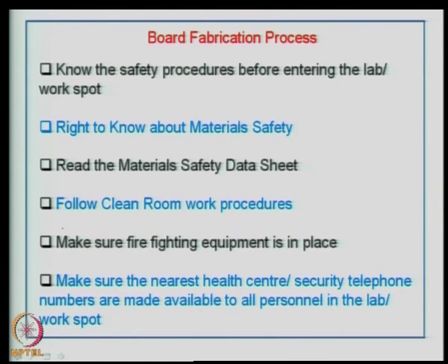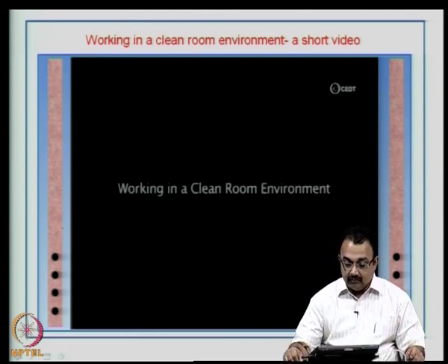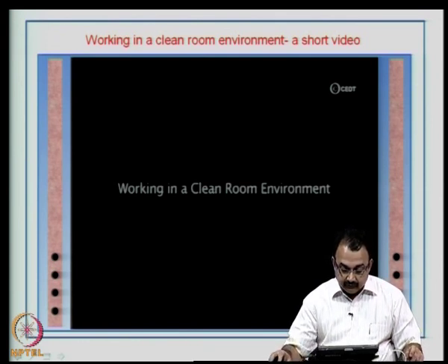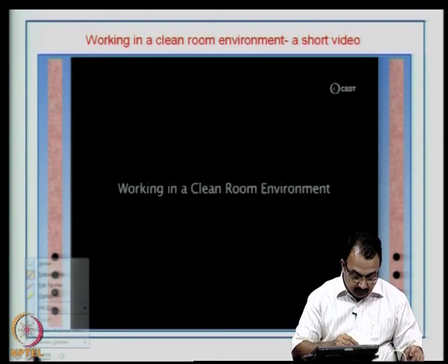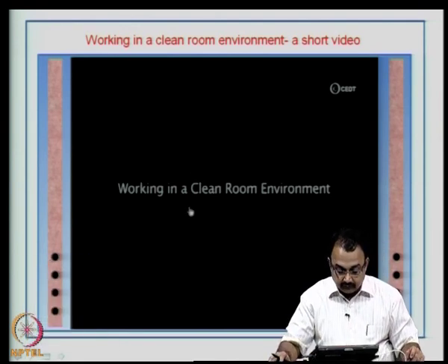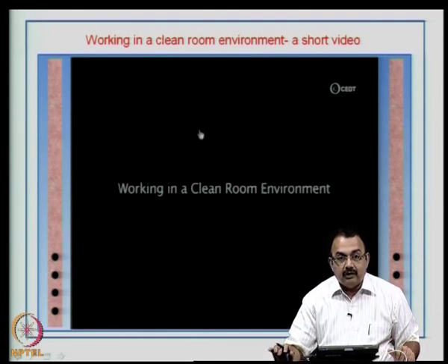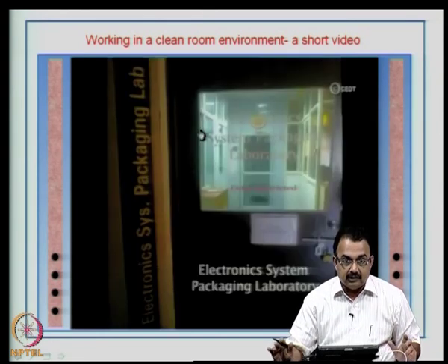So, this is a very general guideline I would like to give for all students and personnel working in R&D and other institutions. Now, we will have a look at typically what it means to have a clean room work procedure or gowning procedure. So, have a look at this video, and I will also try to explain some of the highlights depicted in this video. Your clean room can be, as I said, class 10, 100, 1000, 10,000 and so on.